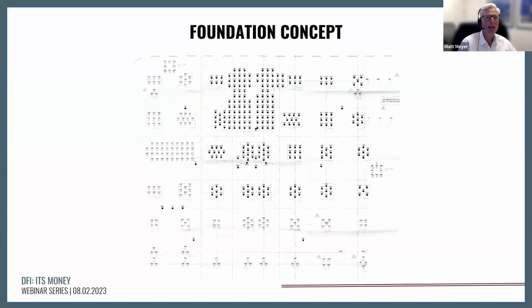So this was the concept that we came up with. About 100 piles or so were a medium length, saving about 45 feet in length in terms of those 100 piles, provided settlement compatibility is attained and provided that stratum 7A is not present. And that was our conclusion at the time when we generated this foundation concept plan.